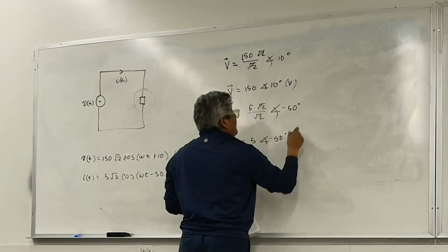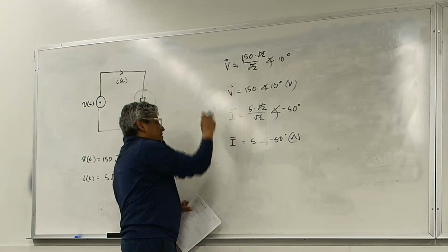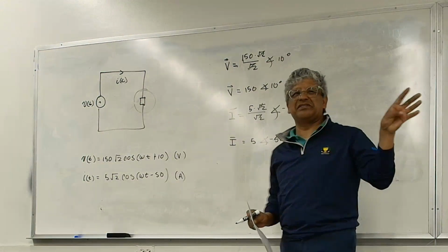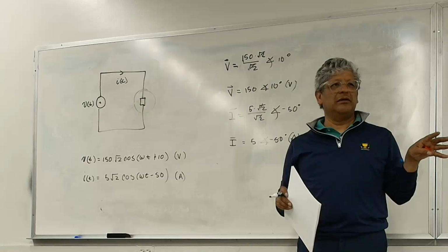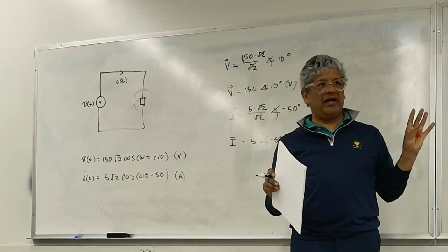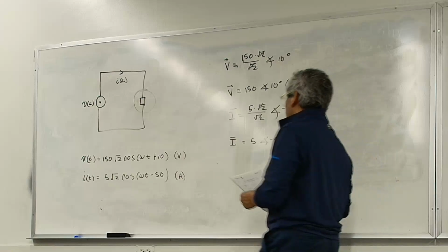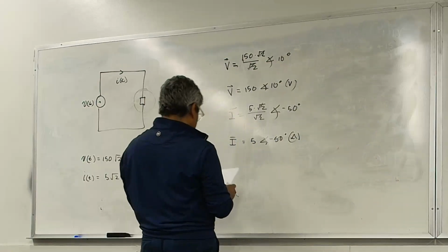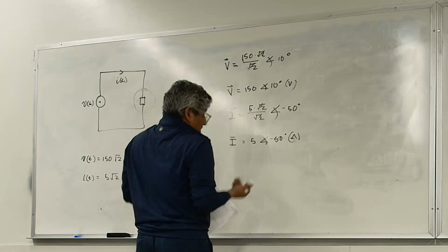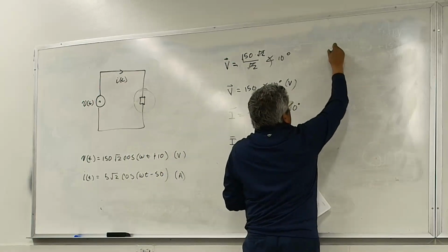Now I know V and I know I. And this is a single phase circuit, so I don't have to worry about square root of 3s. Unless it was three phase, then all bets are off, I'd have to use a different formula and think about line to line and line to neutral voltages. But in this case, that's not something I should worry about. You can say, okay, how about if I theta?